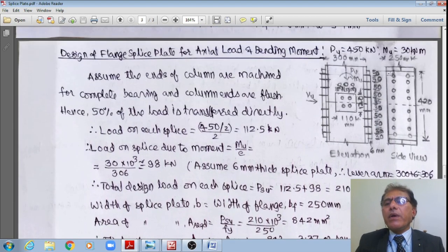Now I'll show in 2 rows. Therefore, 4 plus 4, 8 number of bolts on either side of the joint, right? Therefore 8 here on the top as well as the bottom of this column also. Actually this is not a story but a joint, actually a splice, right? Therefore on the top of this joint or splice, on the bottom of this joint also 8 on either side, right? Therefore these are 8 and these are also 8 and these are also 8, right?